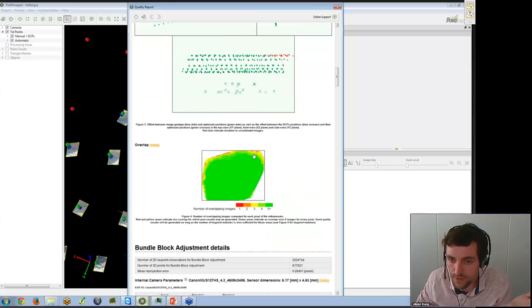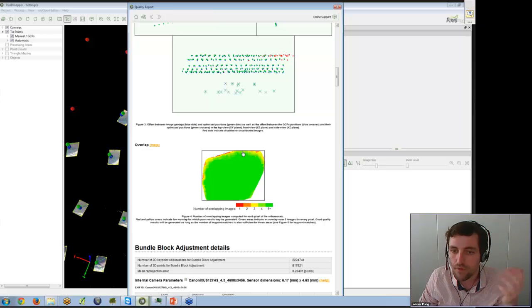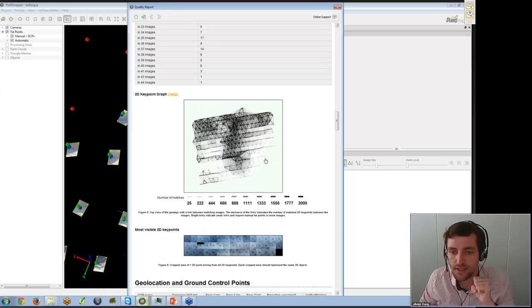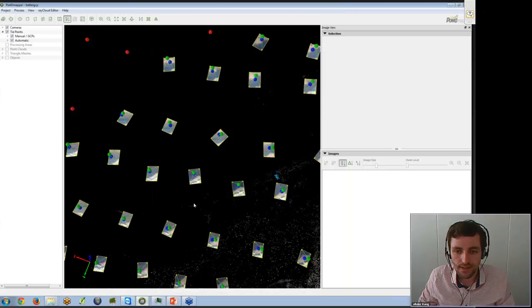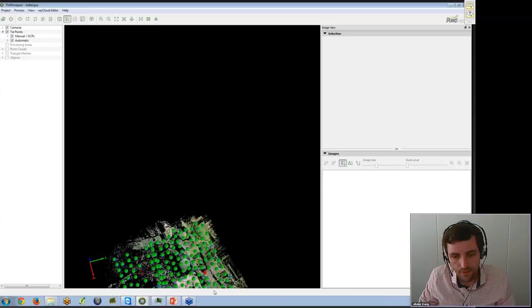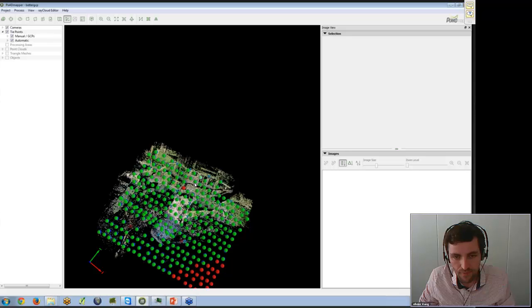The overlap is good. The images were taken with the right distances between each other to keep something like 70% overlap between each image. But something important to notice is that the visual content is not always the same in the whole project. And in this specific project, you can see that very likely there's less visual content on the bottom here than on the top.